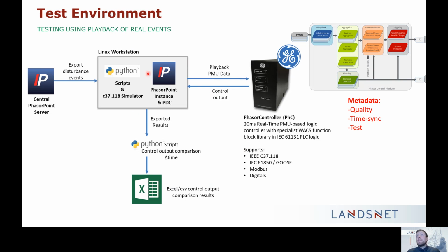And for the testing we did, we have this control platform. We can program any of these wide area control logics just using standard IEC 61131 PLC logic. The input to all of this is the C37 data. But this controller, we usually use 61850 to interact with any of the providers, if it's just giving I/O on the remote end or something like that. So usually we go for the 61850 GOOSE output of it.